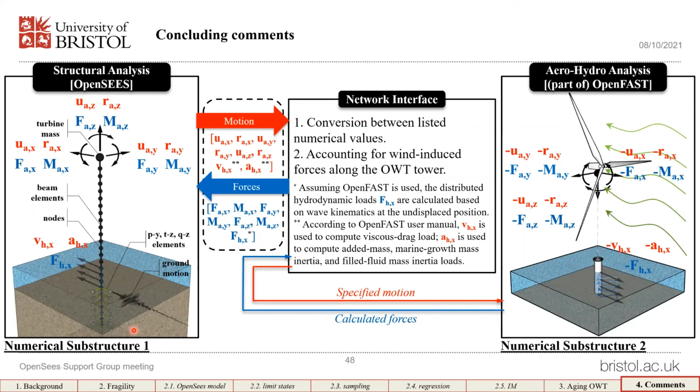Well, that's a very interesting one, because the model didn't converge for me for uniform excitation. Yeah, that's pretty strange. And also I have encountered several issues with the system thing in OpenSees, and also several others. I have to adjust between the different types of available options to make these models converge finally.